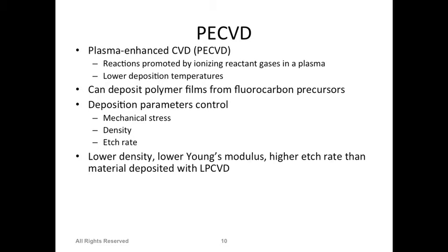Okay, so same thing by lower temperatures. In this case, you can perform the CVD process at about 500 or even less than 500, like 300 or 400 degrees centigrade, like half of what we have to use in the LPCVD process. But the film quality in PECVD is not that great as compared to LPCVD. Because you are depositing at a high rate, you don't get a very good density of the film which we are depositing. But overall it's a very nice technique, especially when you have something on the surface which has low melting temperature.